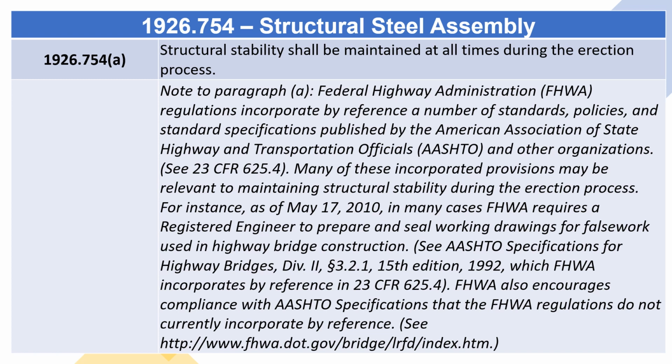For instance, as of May 17, 2010, in many cases FHWA requires a registered engineer to prepare and seal working drawings for falsework used in highway bridge construction. See AASHTO specifications for highway bridges, Div. 2, Section 3.2.1, 15th edition, 1992, which FHWA incorporates by reference in 23 CFR 625.4. FHWA also encourages compliance with AASHTO specifications that the FHWA regulations do not currently incorporate by reference. See http://www.fhwa.gov/bridge/LRFD/index.htm